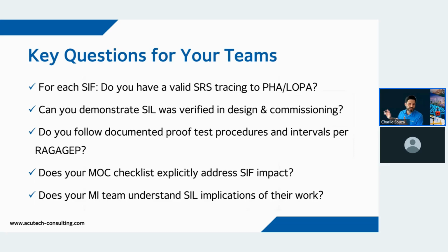and a lot of times move that over to, or postpone that into, your next turnaround, for example, right? One thing is your regular instrumentation. Another thing is your safety instrumented system equipment. Those are at a higher level of safety, and those you may not be able to hold up and postpone into your next turnaround, which you may be able to get away with on your regular instrumentation.